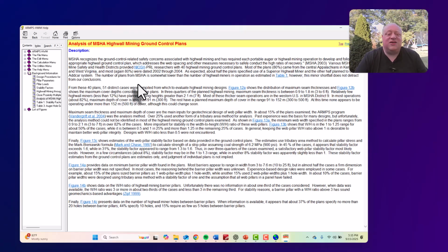By limiting the area, by strategically using barriers or the mining layout, you can use smaller, narrower pillars with width to height ratios getting closer to 1, and still be stable overall because you have these barriers spaced closer together. So the area that you're creating these openings in does matter, and we'll talk about that in the future as well.